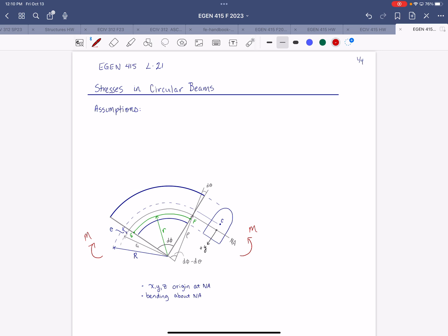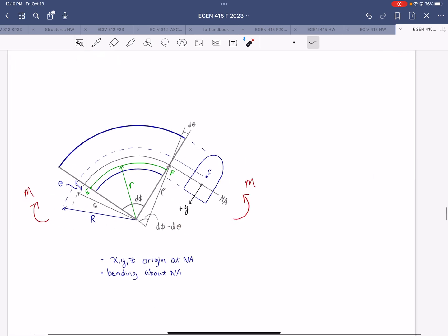What if it's got a circular cross-section? If it has a circular cross-section and it's curved, then I would call it a beam with a circular cross-section that is curved. So we're going to set this up, looking at this generic cross-section shape. The equations that we're going to derive relate to beam bending, and they will be applicable to any generic cross-section shape. Yeah, good questions.